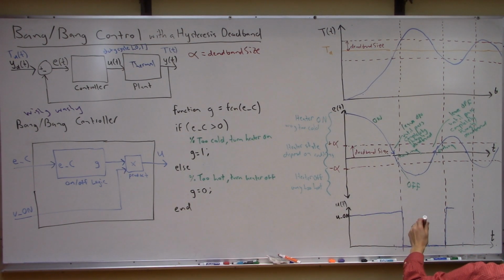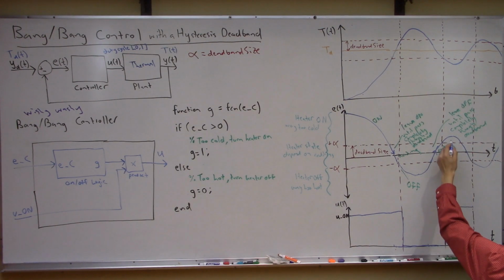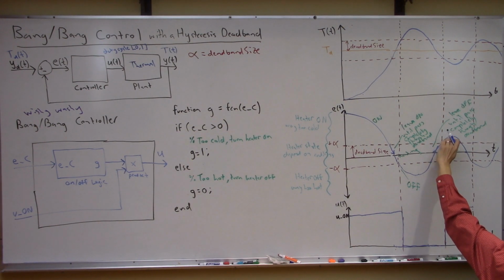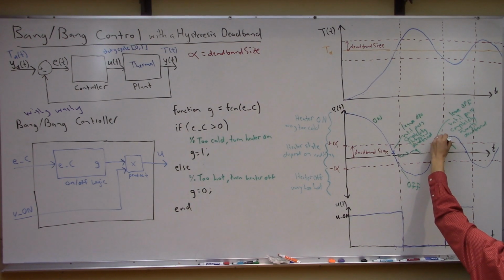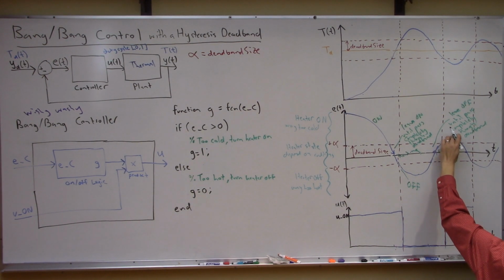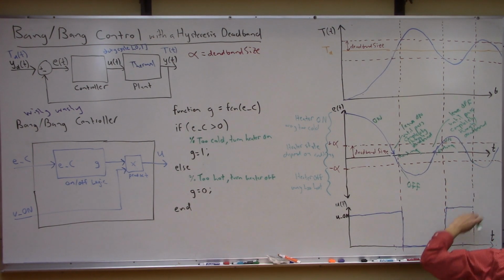Yep. And basically, we just repeat this pattern. I think everyone sees what's going on at this point, right? So now we do the same thing. The heater turned on right here, as soon as you pass out. And we stay on, and again, you enter the deadband, and we commit. We commit to heating all the way through, so it's still on, until you leave the deadband completely out here. So you get this,